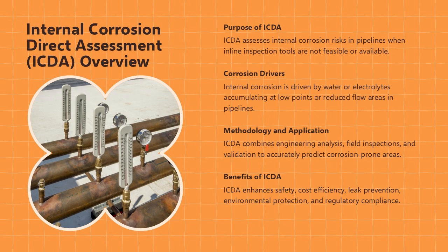ICDA is particularly applicable to pipelines transporting refined products, crude oil, or other liquid hydrocarbons where free water may be intermittently present. The methodology integrates engineering analysis, field inspections and validation activities to ensure predictions are accurate and defensible. When properly applied, ICDA supports integrity management objectives by preventing leaks, protecting the environment and ensuring regulatory compliance. It is not a one-time activity but part of a continuous improvement cycle that evolves as new data becomes available.